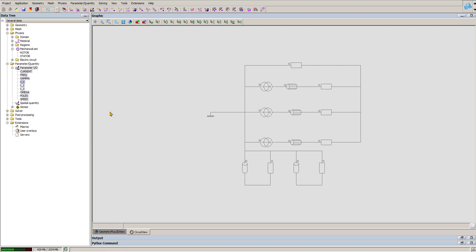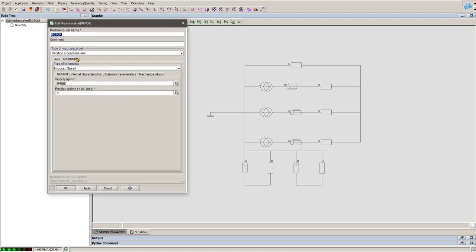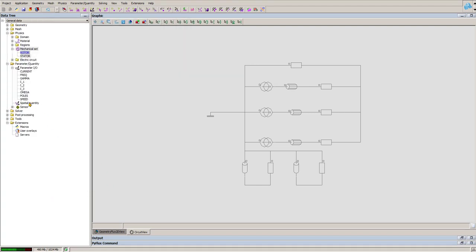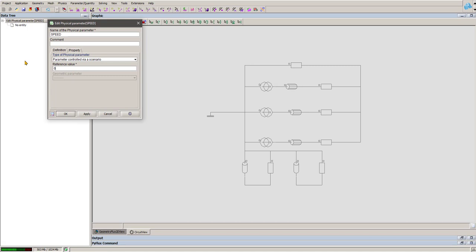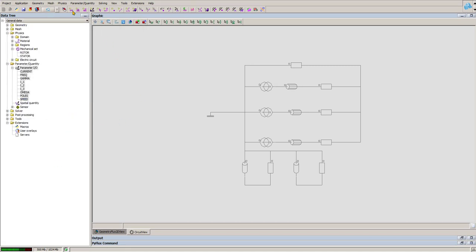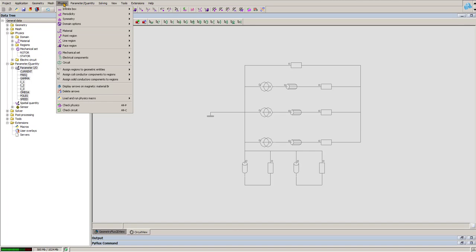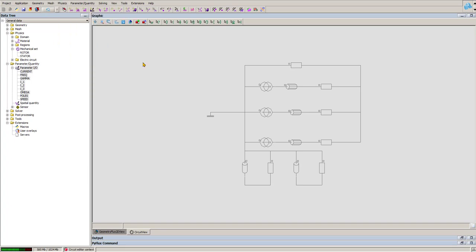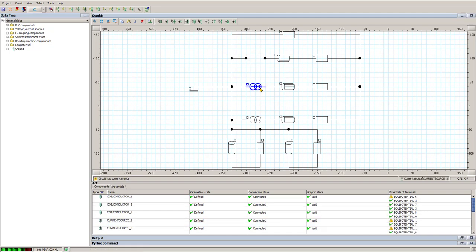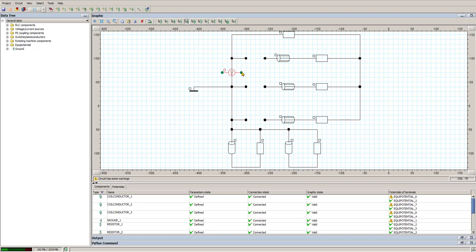Okay, I want to modify this project in order to determine the stall torque and the stall current. So first of all, I have to go to the rotor and impose the speed equal to 0. This is what I want to do. So parameter speed, I will switch it to 0 here. And then I have to modify current sources to voltage sources, delete them all, and impose voltage sources like this. And I will rotate them.